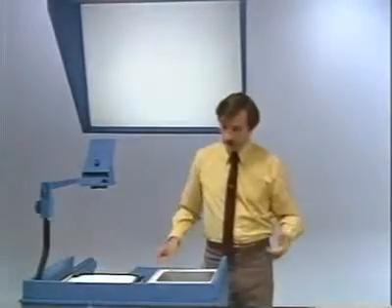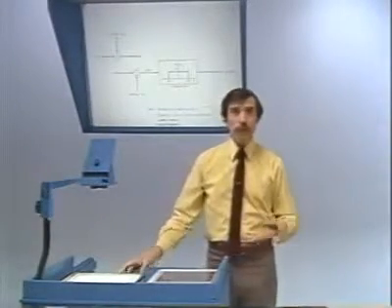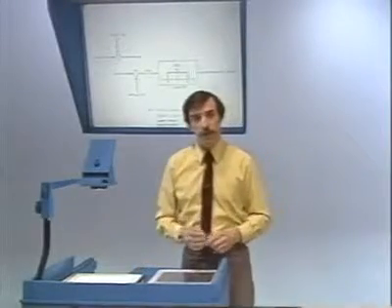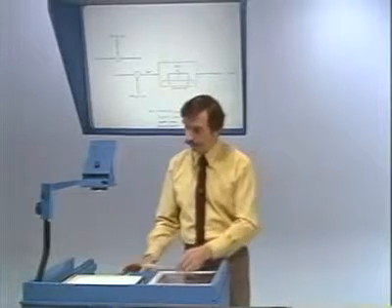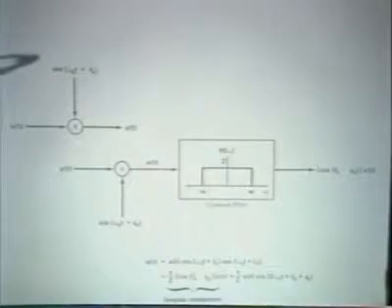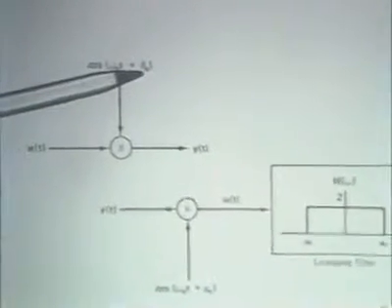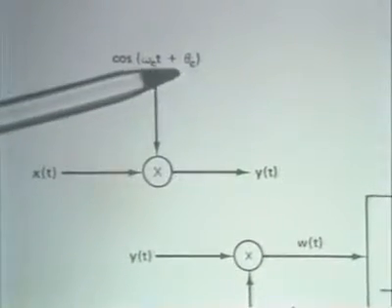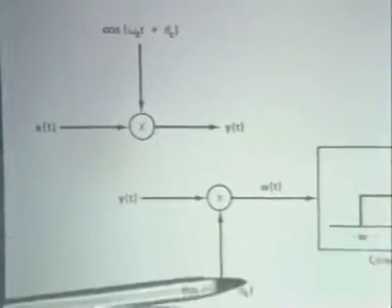And there also, by the way, is another problem, which is the issue of synchronization in frequency. That's examined more in the text, and what I'll focus on here is just the issue of synchronization in phase to give you some sense of what the issue is. Okay, so now what we want to look at is what happens if we have a modulator with phase theta sub c and a demodulator where the phase, instead of being theta sub c, is some other phase, phi sub c.